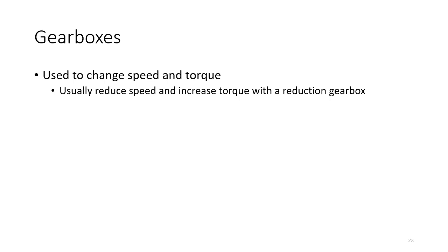Gearboxes do have their issues. A couple of main issues. You have to think about backlash. When the gearbox changes direction, because of the way the teeth interact, when you reverse there's a slight movement before the teeth engage in the opposite direction. That's called backlash.